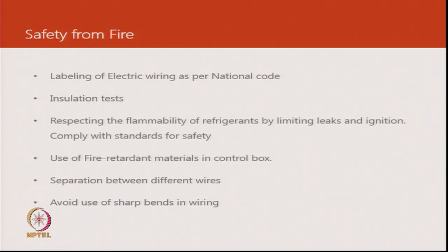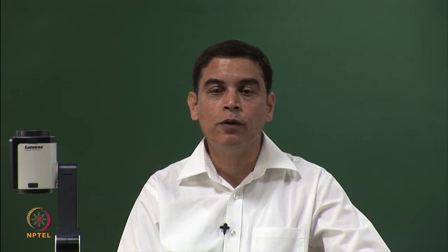And then during design there are reliability and safety tests that can be done. You create ignition deliberately. One of the things we did for residential products was to put fuel in the control box. You take a cotton swab, say about 5 to 10 ml of petrol, you put it there and then you deliberately spark there, and there is a flame. Then you can look at scenarios with a fire retardant material and without it, and the degree of spread, and that gives you some satisfaction that if you've designed it well, the fire will not spread, it will just extinguish within the box.